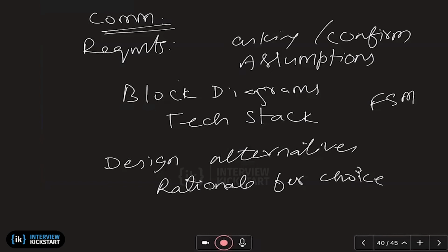So you have to know whether your platform can support those things, like software update. Is there sufficient flash memory to have two or more images of the firmware to do an over-the-air update? Again, those are the choices that you would make from a deployment perspective.